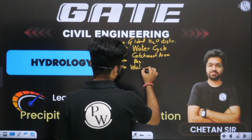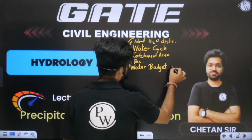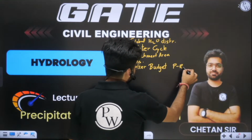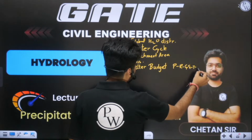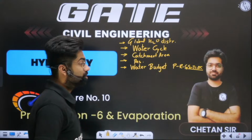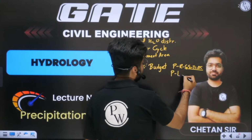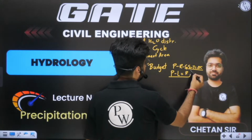Very, very important. Many questions have been framed in past year papers regarding this equation, and the basic equation is P plus R plus G minus E minus T equal to delta S. This is the main equation, and on assumption basis we have simplified it and reduced it down to P minus losses equal to runoff. Okay, so this was our main equation.